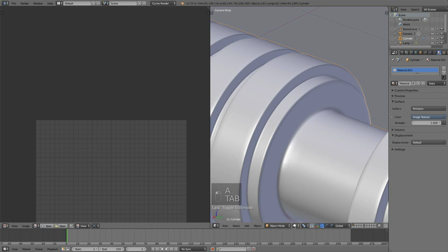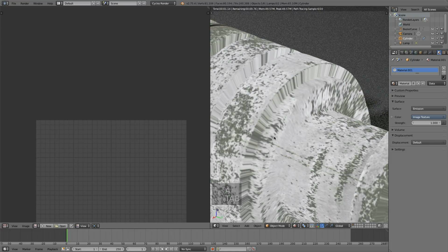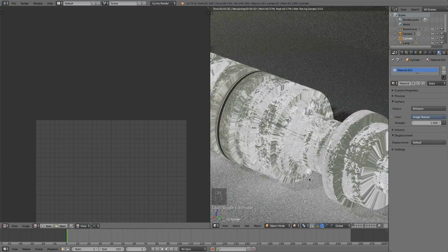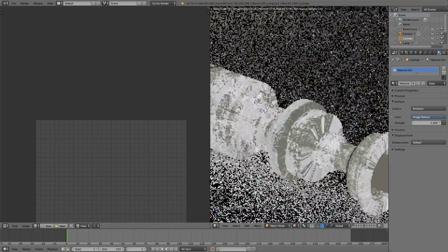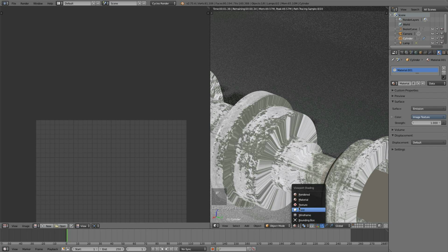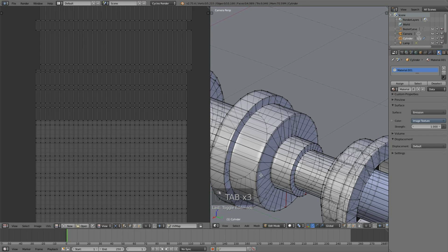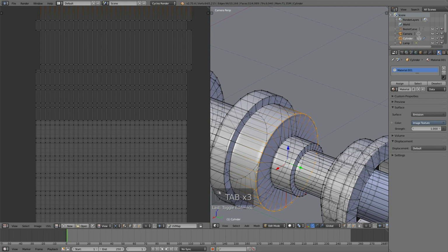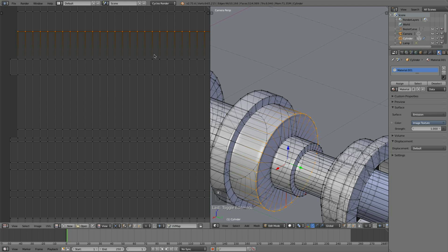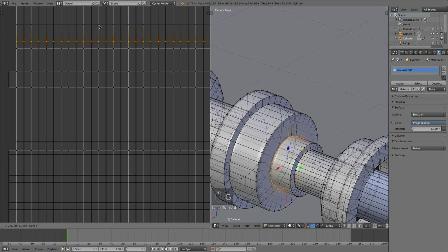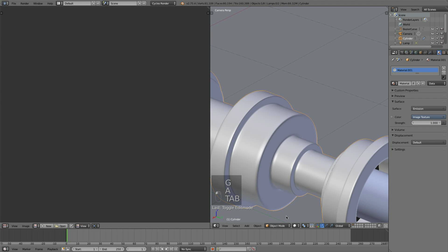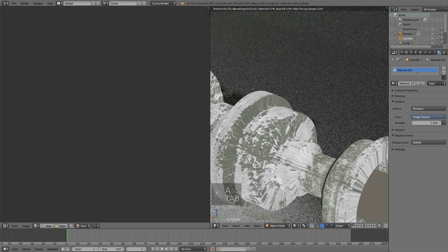Now when I go rendered, you should see it's not nearly as stretched in that area, so it's a lot better. So that's how you can tweak your UV mesh, and just a few areas need it, like this one here could use it. So I'm going to do the same thing there real quick. Grab those two vertices, grab it along the Y-axis, and give it some room. So the texture is no longer stretched, at least not as badly. And there we go. If we get rendered, it should look much better.